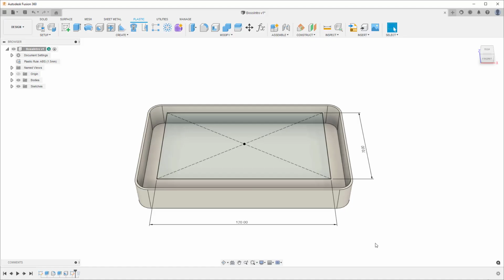The sketch geometry, more specifically sketch points, are what drive the location of each boss. You can use existing planes or faces to start your sketch, and, with the use of constraints or dimensions, you can precisely position the reference points.